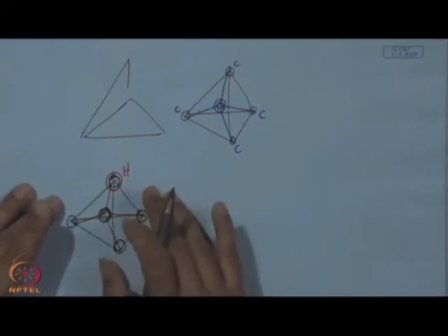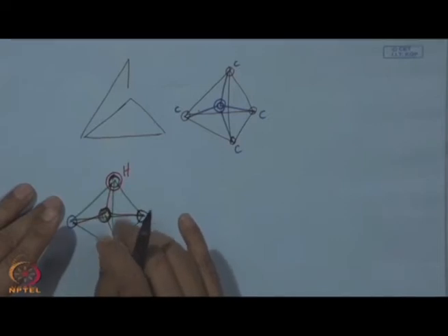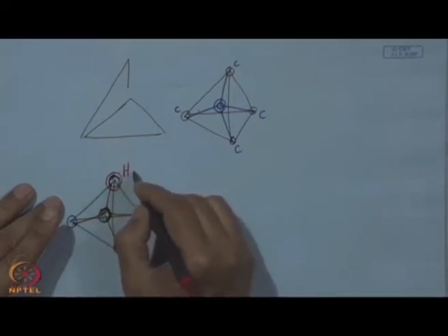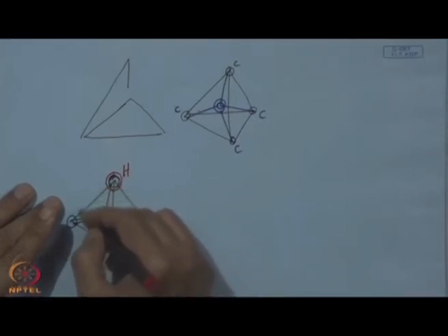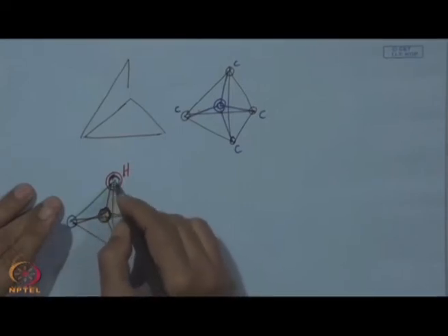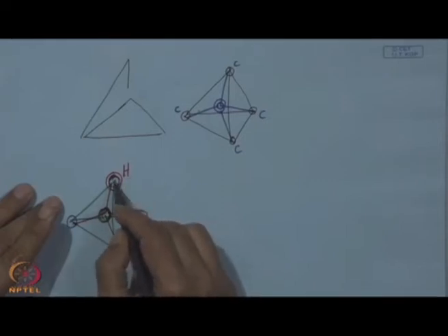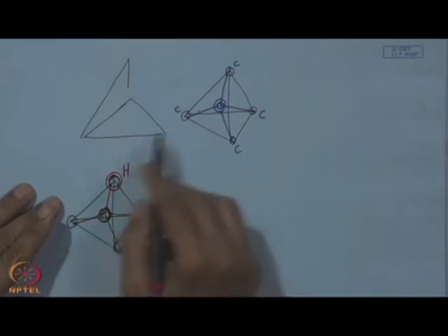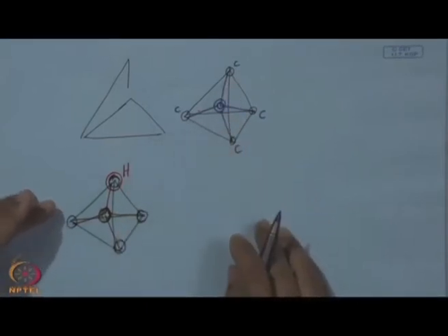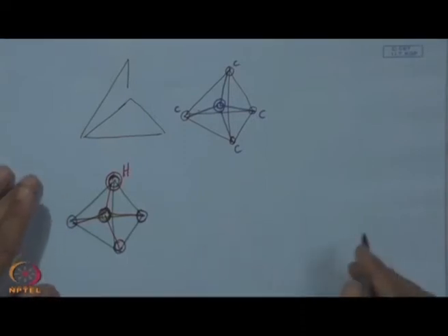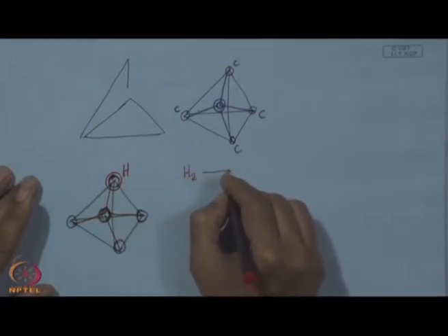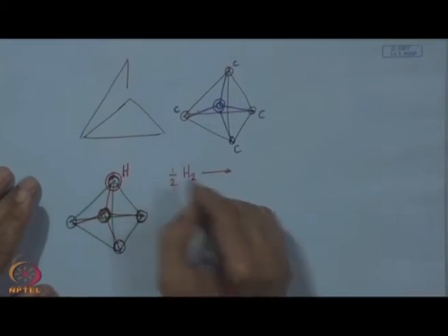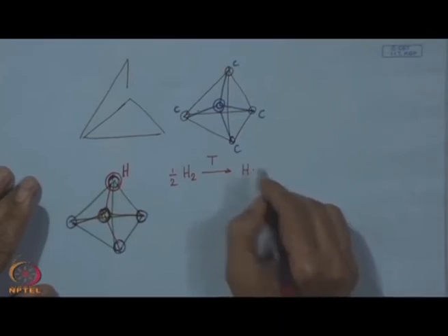Now, the whole idea here is that when we have this seed of diamond, this particular hydrogen will be removed from this place and it will be replaced by one carbon, filling the entire structure of this diamond with carbon. If this hydrogen is removed or stripped and substituted by another carbon, then again we have a complete lattice with this tetrahedral form of diamond, and exactly on this principle the CVD process works. So, the first task would be to have this hydrogen, which is molecular hydrogen, that is the first step of the CVD reaction, and which is thermally activated, and it becomes nascent hydrogen.